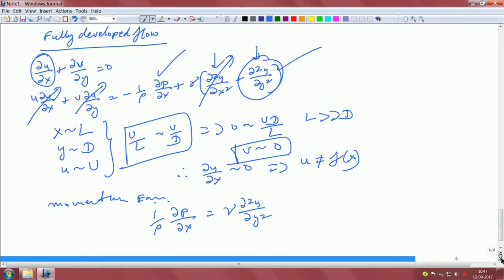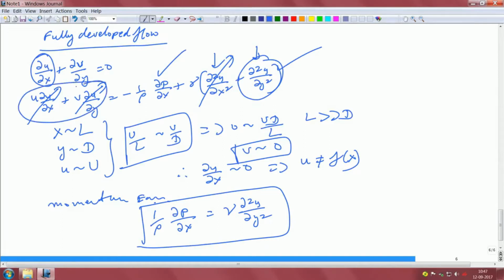So, that would be an interesting proposition. When you look at the momentum equation in this particular form, you will find that the flow is obviously moving, but it is a non-accelerating flow, because the convective derivative, which is the convective part, has gone equal to 0. Okay. So, there is no convective derivative, or no convective acceleration, that is equal to 0, right.